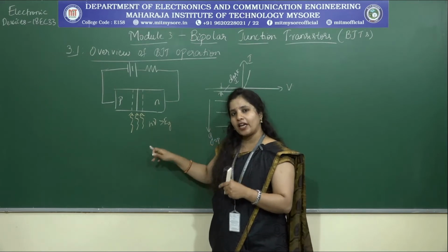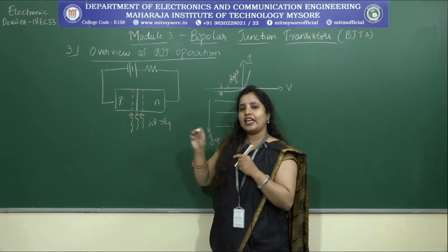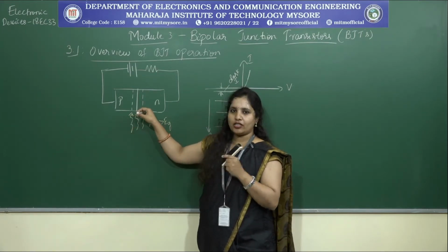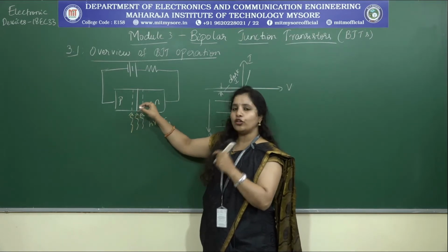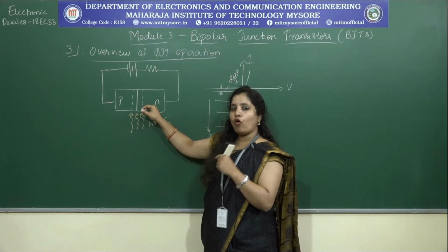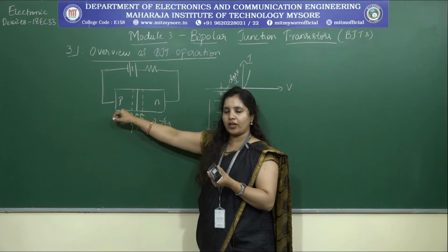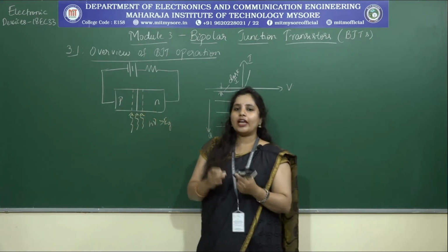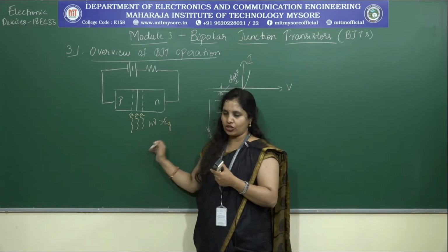Instead of optically generating those EHP pairs, if I can inject minority carriers, say holes, into this n region, the more charge carriers I inject, the more sweeping of charge carriers and the more reverse current. So, can I provide such an alternative solution instead of optical generation?